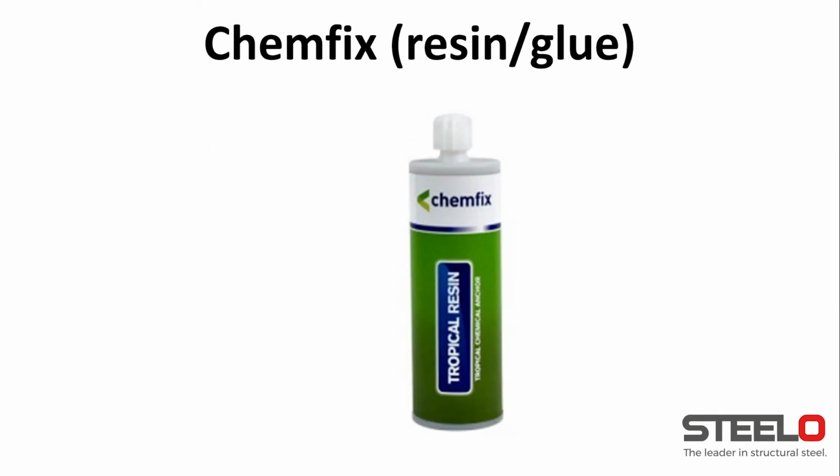Chemfix is the name of a manufacturer who does a wide range of resin or glues. They're normally two-part glues, so they get mixed up once you press the gun, and it mixes itself going through a nozzle, and then once the mixture is ready, it dries out and bonds the stud into the concrete slab.